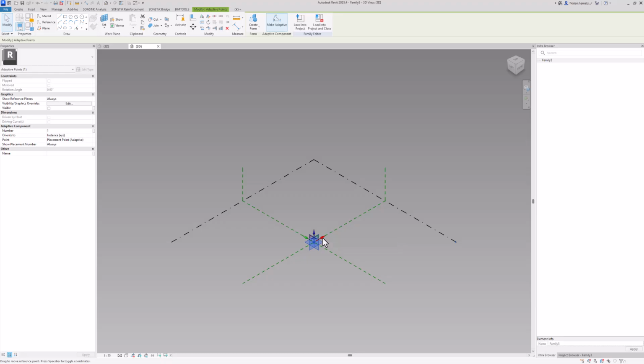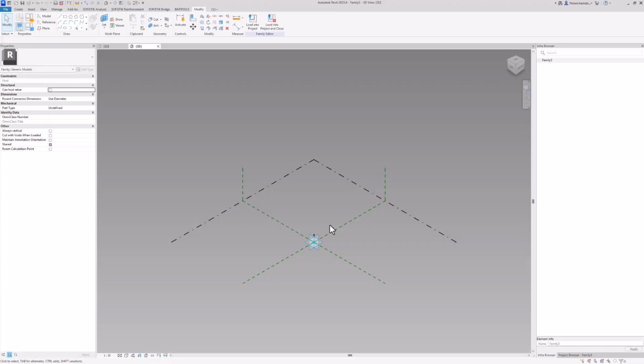The family that we want to create is rather simple. It's basically a rectangle. But as we want to, on the one hand, control the interval in which it's going to be placed, which is the amount of adaptive points with families that will be placed along the axis, this is done via the bridge modeler. So in the family itself, we don't have to bother with that. But what we want to bother with is the width development of our beam later on. This is a functionality we can simply access via variables of our main axis. But we have to create parameters within the family.